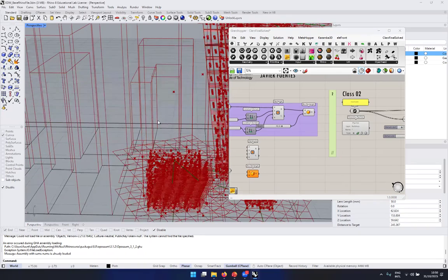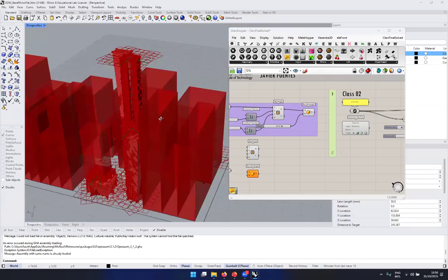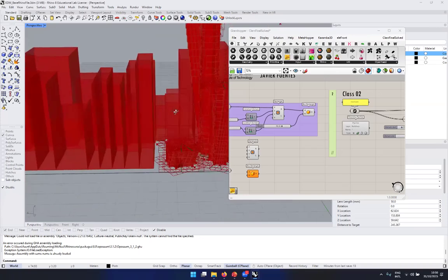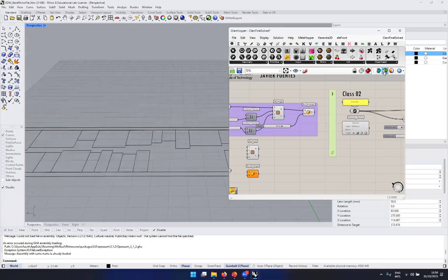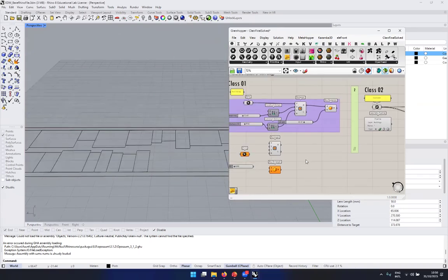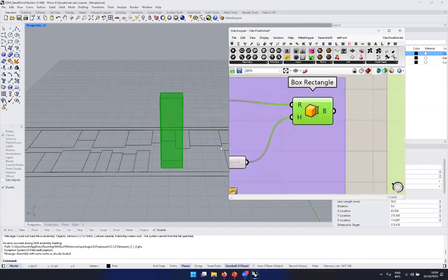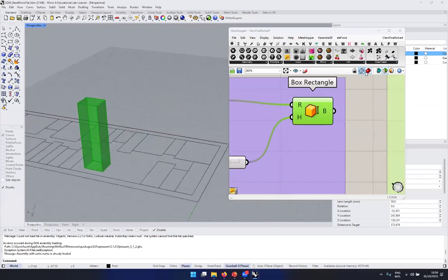Usually, if your Grasshopper runs slowly, you can select wireframe display, and this will make it faster. If you select shaded, you see mine now is a bit laggy. It's a bit slow. But take a look. If I select this one, it means that I am only going to display what I have selected. If I select my box, I display my box. How? With the 3 display types that I have: shaded, wireframe, no display.